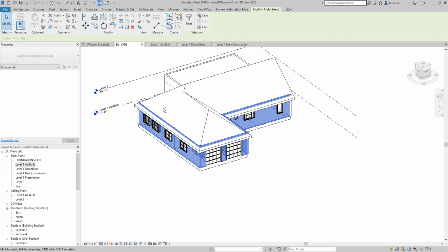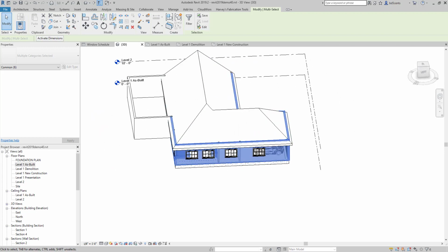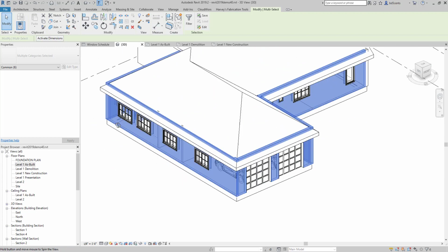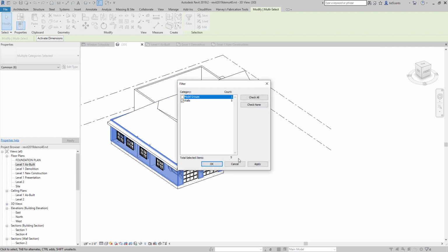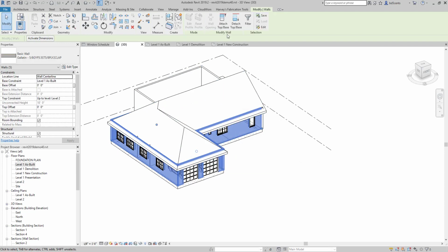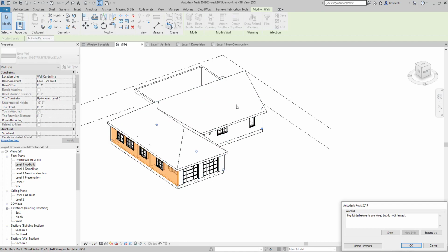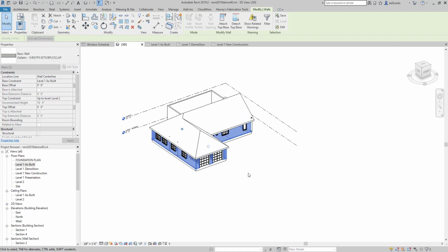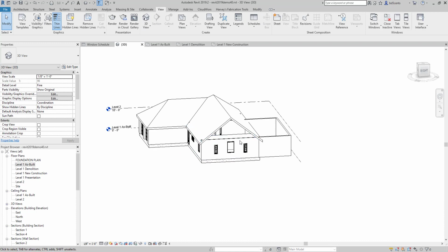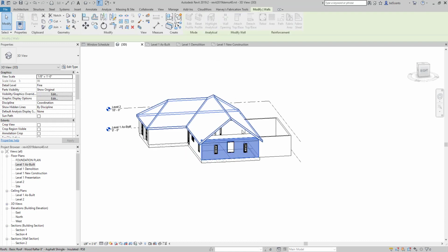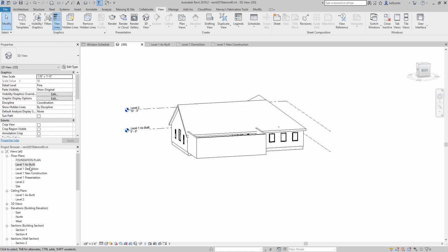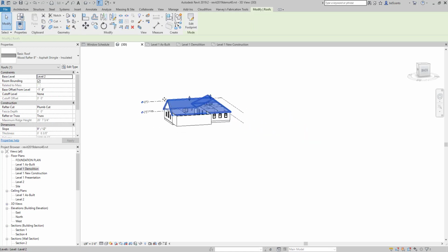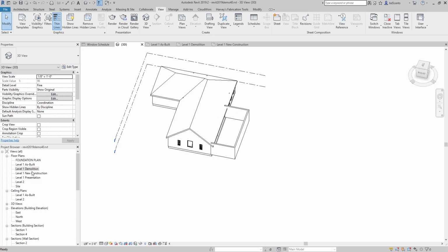I'm just going to go in here, select all my walls. I can check my filter if I'm not seeing what I want. I have a model group selected accidentally, and now I know that I can attach. So as long as I have the wall set up correctly, that'll attach correctly. And now I'm starting to get a house. Attach. And now we'll just draw on the new roof addition, which technically will make that modification.